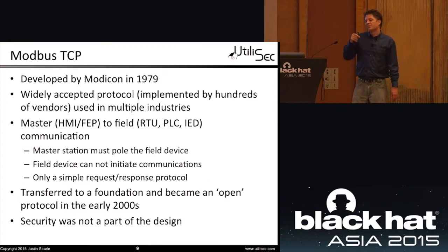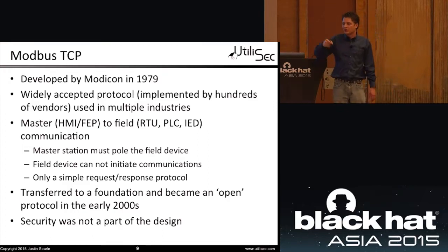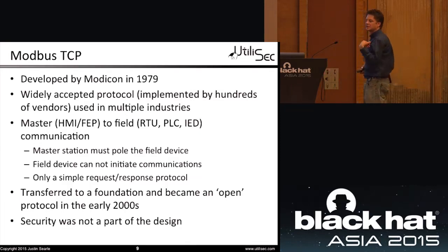So what we call is we have the master that is polling the different field devices. He will poll them to read values. And often these will be very discrete, synchronized read values. Inside of SCADA, like I mentioned, a lot of electric utilities will do reads of their substations every 2 seconds. So we're constantly going through, and the master will say, okay, what's the current status now? What's the status on all the sensors? And it pulls that back into the master.